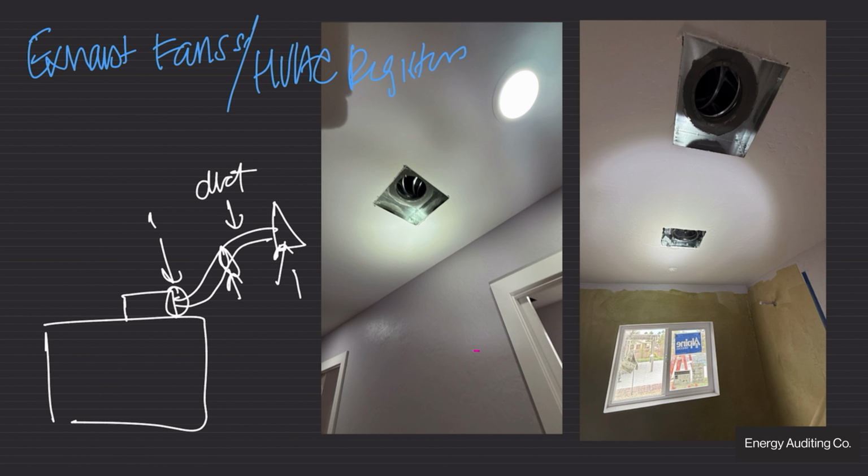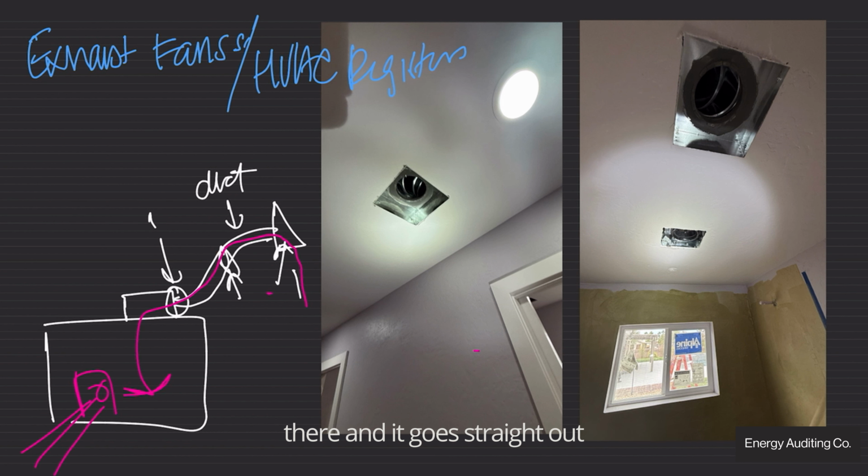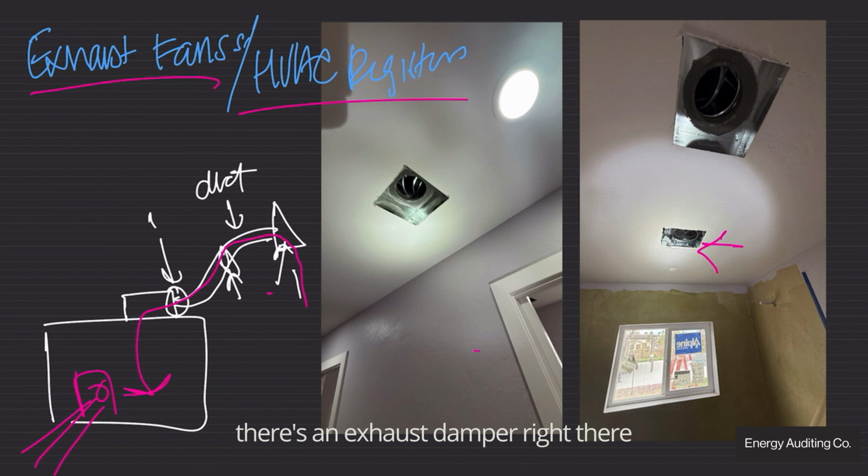It'll honestly just, like, we depressurize the building, and then what happens? The air comes in right through there, and it goes straight out. So that's another place where you can typically fail this test, is that if your exhaust fans and your HVAC registers aren't well sealed. There's an exhaust damper, I believe right there. We'll want, yeah, that's the one that needs it, the damper and everything. So those are kind of like the common areas.